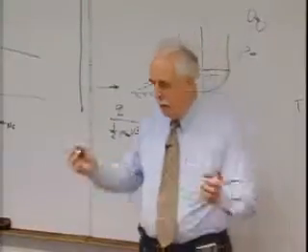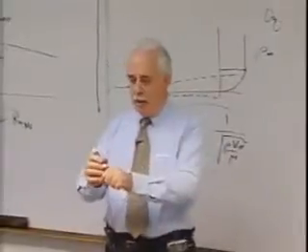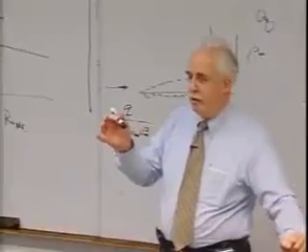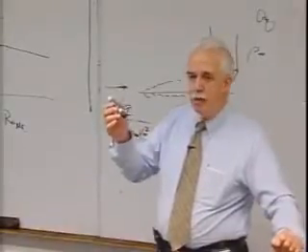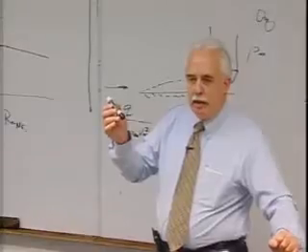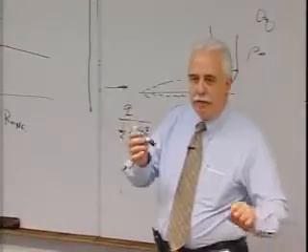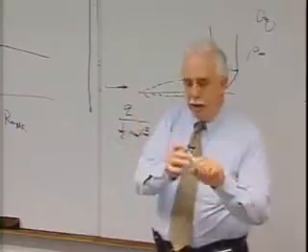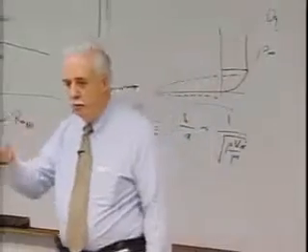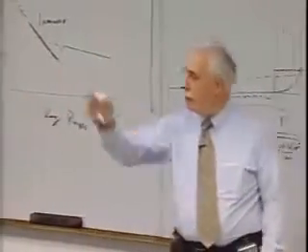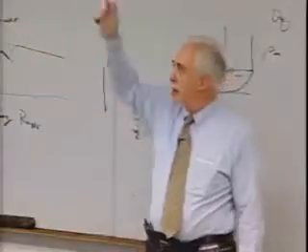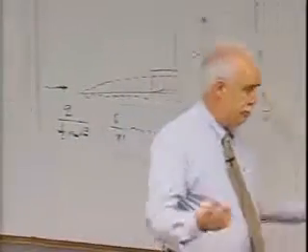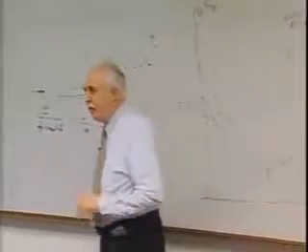Everything went well. There's a spring between the capsule and the boost stage, and they separated, by design, fine. But what happened was the booster lined up with the wake of the incoming test vehicle and just rode the wake because there was a lot less resistance with the air that's being sucked along with it. It clobbered the back of the vehicle and it nutated. And so we weren't looking at the stagnation point, we were looking off at 30 degrees. Not only that, but the radiation was doing this. We figured out the problem, sorted it out, had a second flight test, and it worked beautifully.